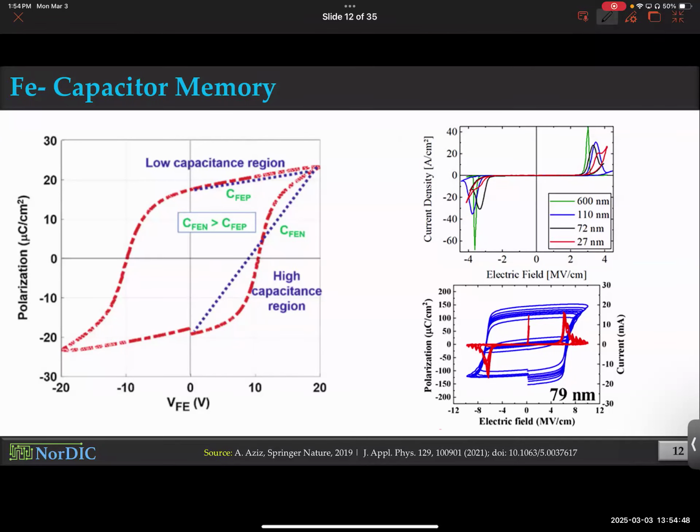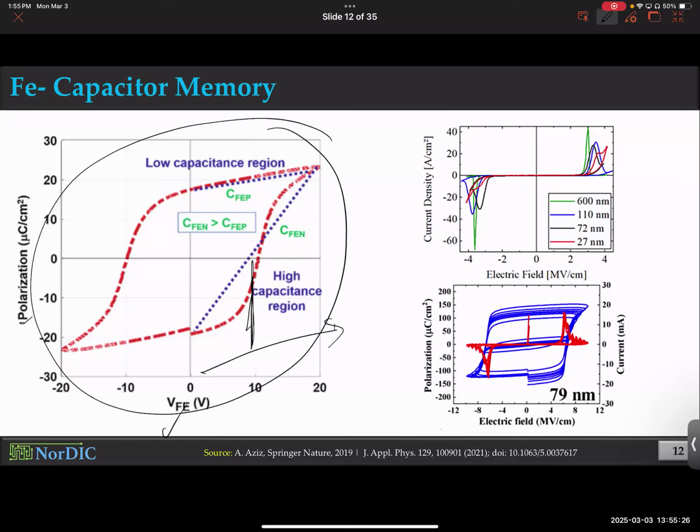Anyone? Yes. It's a good point. Imagine that by doing some interesting circuit design, we can capture that spike. Okay. I can give you a circuit which captures the spike. Even then, there is a challenge. Yeah, there is, because you know which ferroelectric you are using. Okay. And you can test out the polarization versus voltage characteristics of a standalone ferroelectric that you put in. Is it PZT? Is it HZO? You know it beforehand. So you know the coercive voltage, so you know how much voltage to apply to get through. Yes.